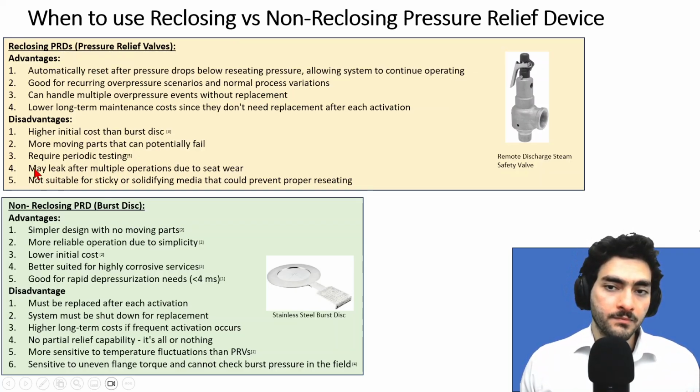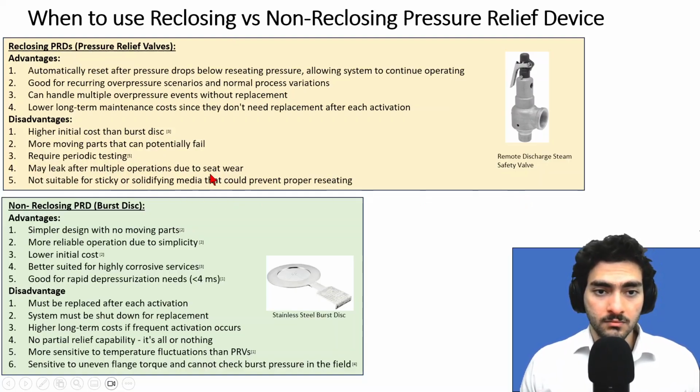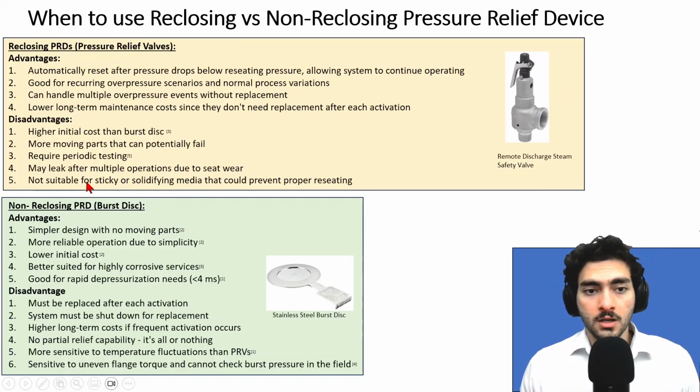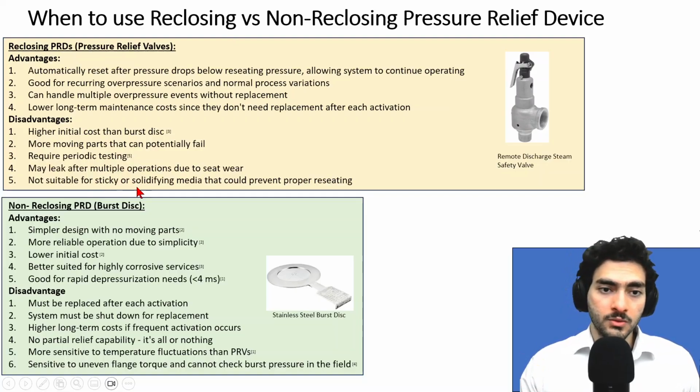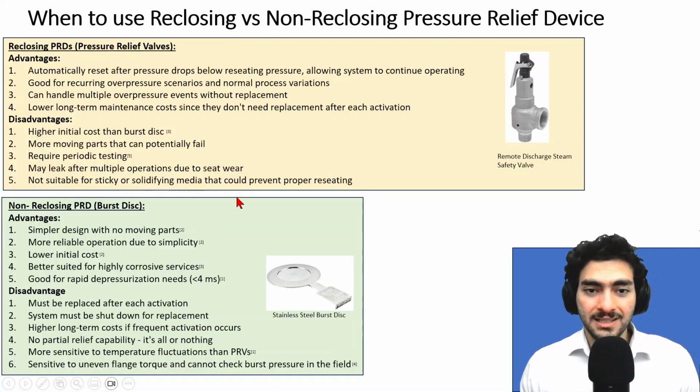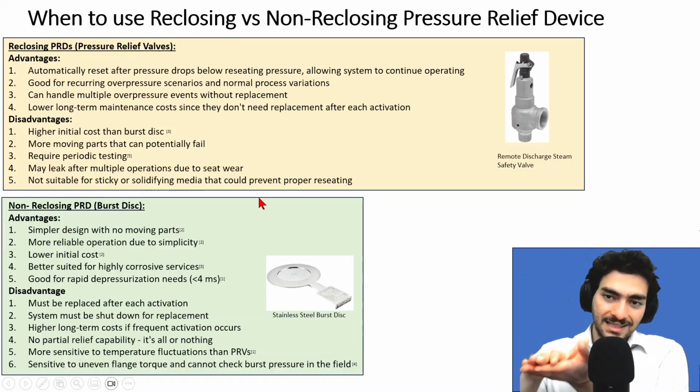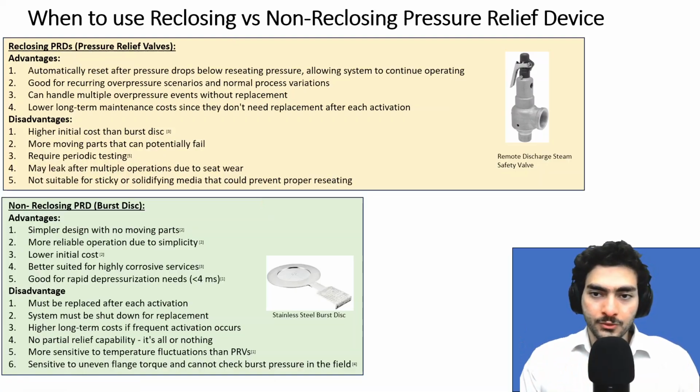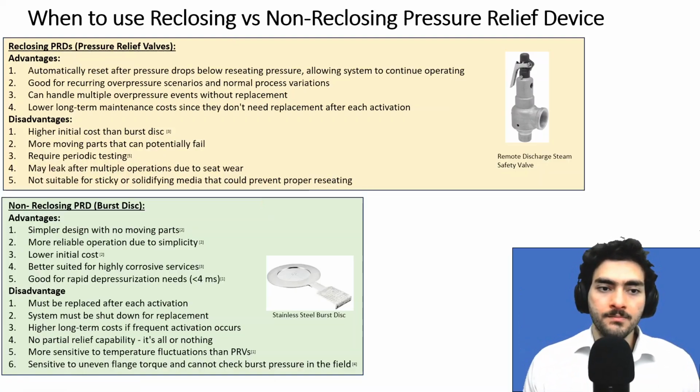And pressure relief valves could also leak due to the wear in the seat. And pressure relief valves are not suitable for process fluids that have solids, or for any sticky or solidifying media that could prevent the seat from properly reseating after it activates.